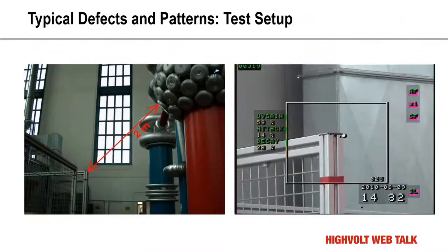Another very much important issue is also that the typical way is that you always look to the high voltage potential as the root cause for any discharge. Nevertheless, this is a very nice example that the fans, which is very close to the test equipment, could be also the source, and therefore the grounding electrode has also to be under control.